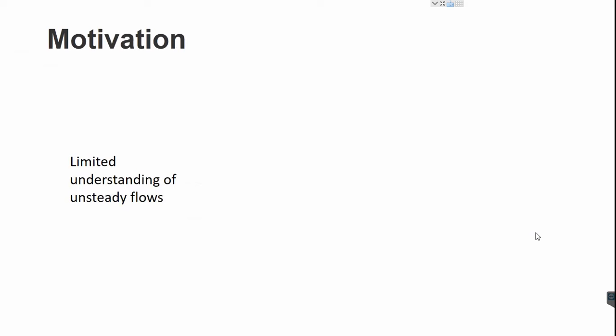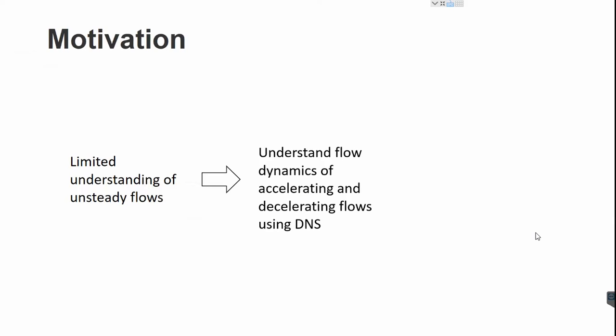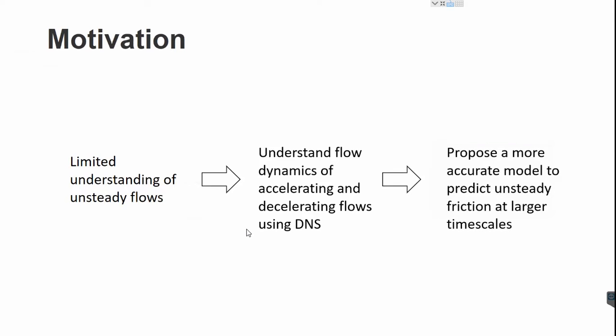So from a fundamental perspective, we want to understand these flow dynamics of accelerating and decelerating flows using direct numerical simulations. In this case, we're not going to do pulsatile flows. We will do just linearly accelerating or decelerating flows. And once we understand these flow dynamics from a fundamental perspective, we will try to propose a more accurate model to predict the unsteady friction during larger time scales.